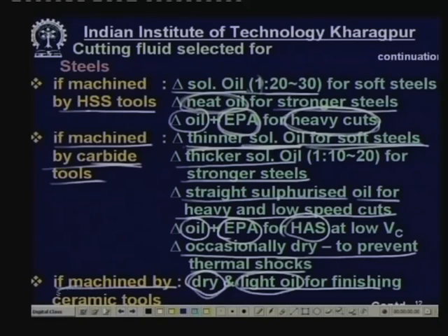In that case, the ceramic tool has to be high performance ceramic with adequate strength and toughness, otherwise this will fracture into pieces because of this water based or soluble oil.